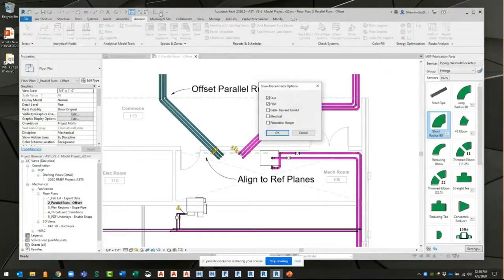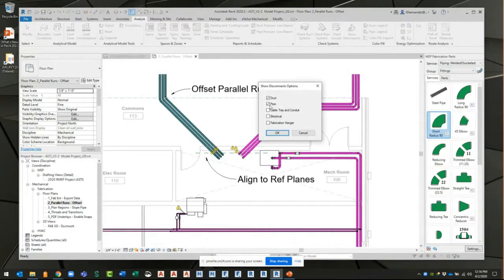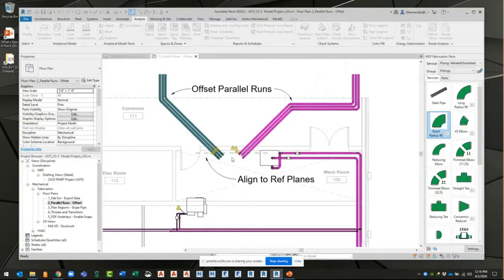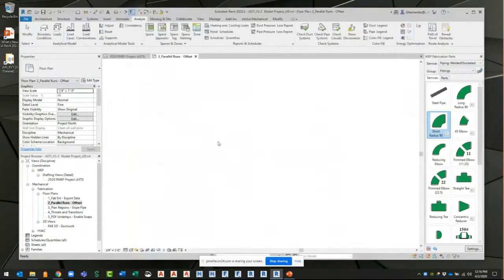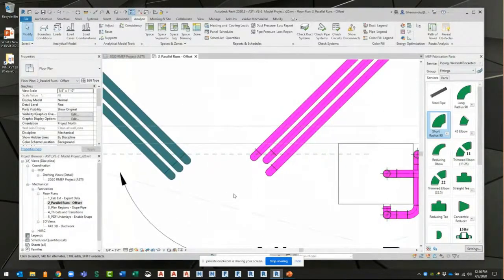And the reason why I put it up here is because you barely are going to come into the Analyze tab, and it's over here on the end. It's kind of hiding. So I put it in the Quick Access toolbar so I can get to it and turn this stuff off so that those yellow triangles of hope kind of go away, okay? So I put the Align command back up there and my Show Disconnects. So let me show you what I was going to get to here.